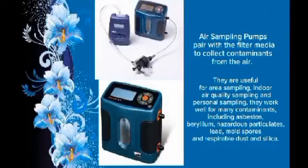Air sampling pumps pair with a filter media to collect contaminants from the air. They are useful for area sampling, indoor air quality sampling, and other personal sampling. They work well for many contaminants, including asbestos, beryllium, hazardous particulates, lead, mold spores, unrespirable dust, and silica.